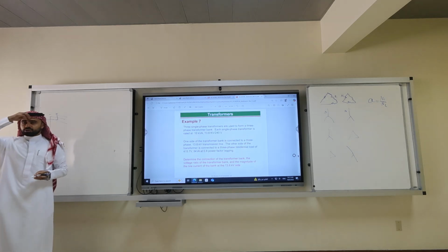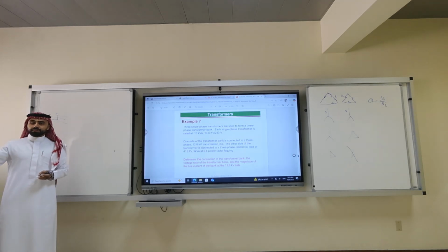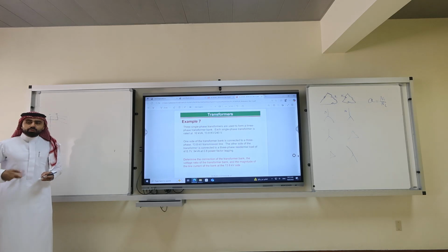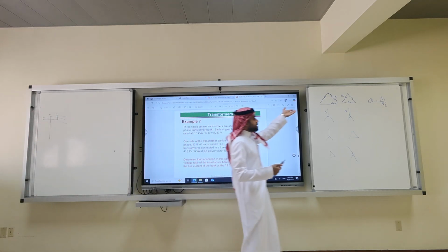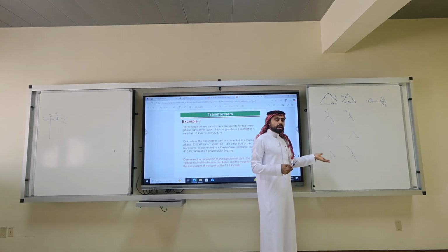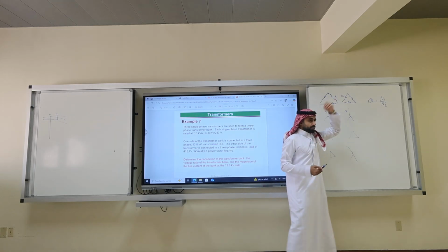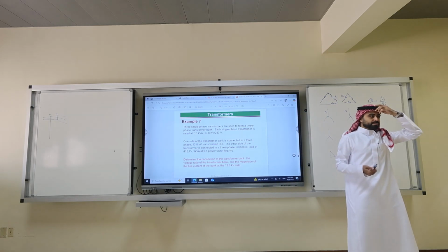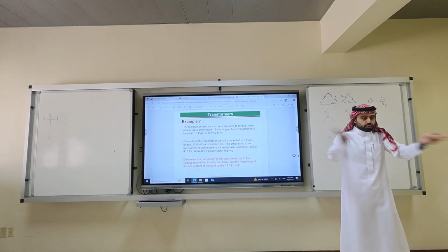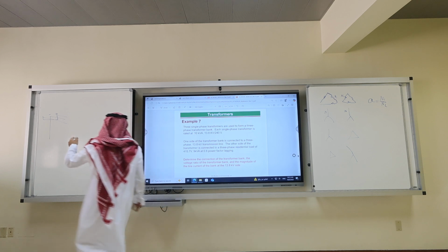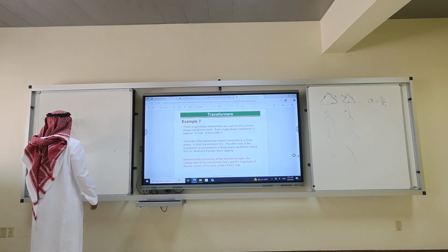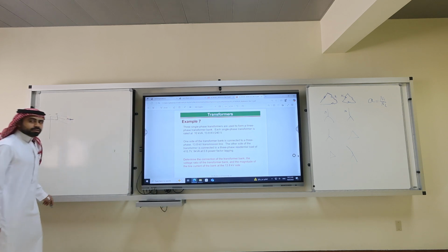Do you remember we love line to line? We cannot say we love line to line in the transformer, because line to line in the transformer depends on the connection. Instead we love coil to coil, because transformers have 2 ways of connection. So this delta is 13.8 kilovolts. You agree with me?